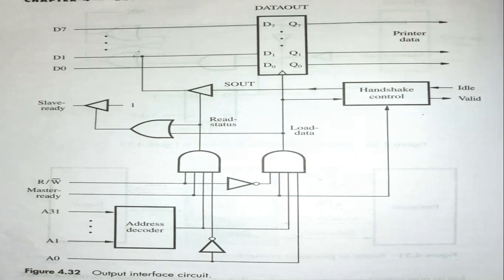As I mentioned, D0 was utilized for sending the S in signal in the previous lecture. So the S out signal will be sent through D1. Now you may ask how this S out will be generated. Here we have a controller available. Observe it carefully. This is a junction. It is responsible for generating the S out signal, and it is also responsible for generating the valid signal.